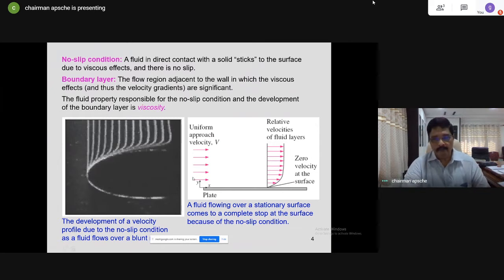So, the essential difference I was talking about was that the fluid, just before hitting the plate, was completely at free stream velocity, at the same uniform velocity it was coming. But once it comes onto the plate, the solid zone, obviously the flow pattern is slightly disturbed. Particularly, I was explaining using that diagram. Particularly when fluid flows in the immediate vicinity of the solid plate, the frictional effects cause the velocity to vary immediately, right on the solid boundary.